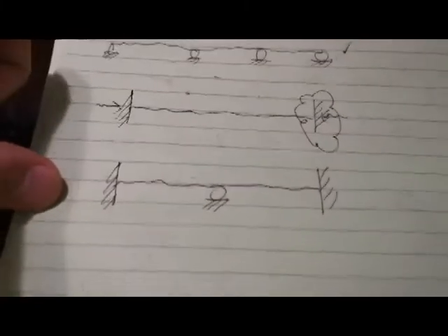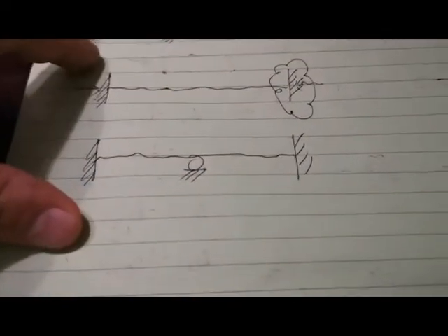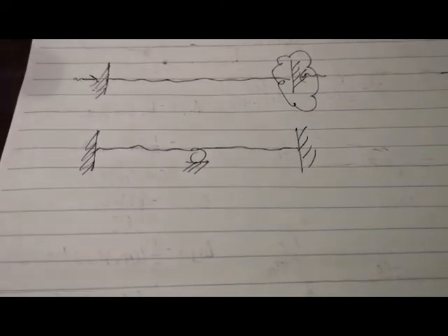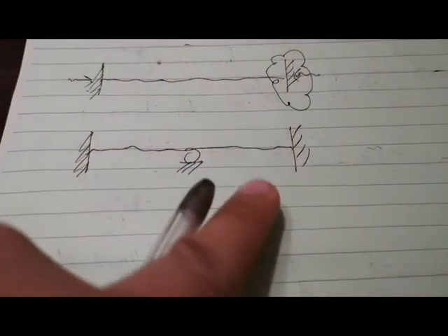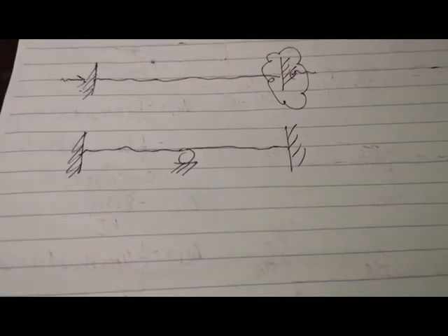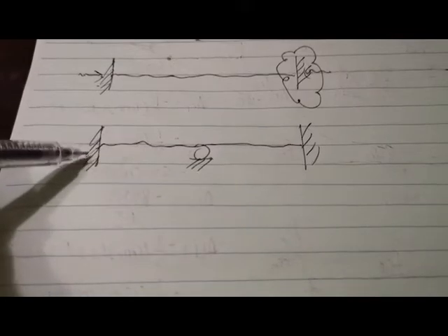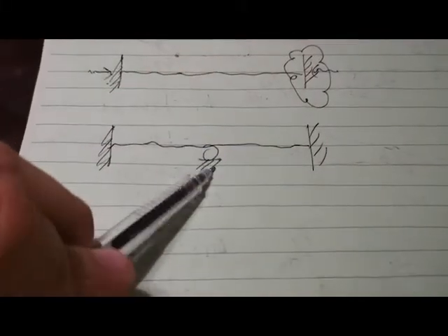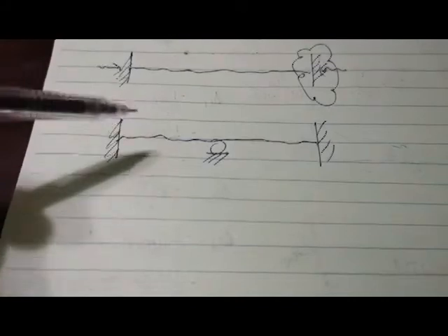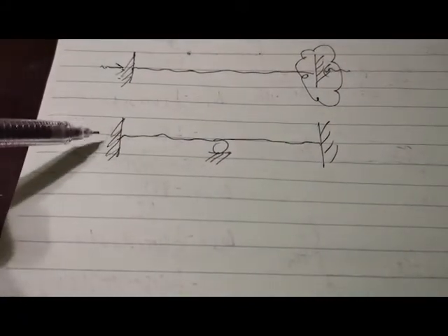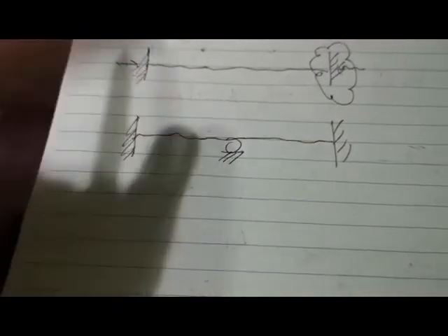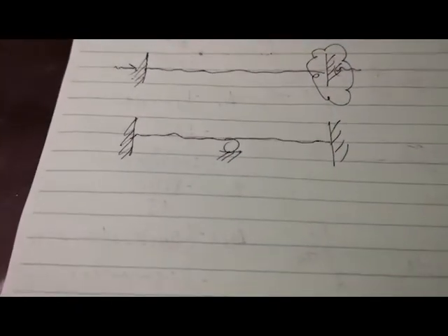Okay, so this is somewhat similar to the machine problem that I gave you recently. In order for you to have a clue on how to solve this, you can either remove the support here and the support here to make it a fixed beam, or remove the moment on the left, the moment on the right, then the moment in the middle to make it a simply supported beam.